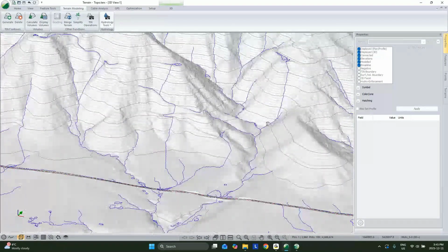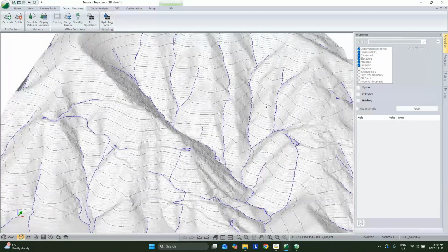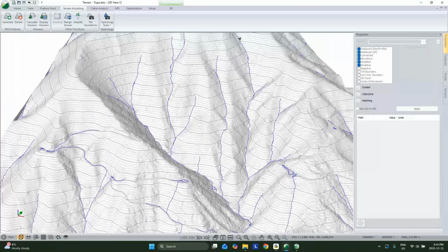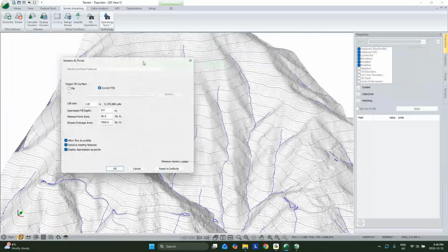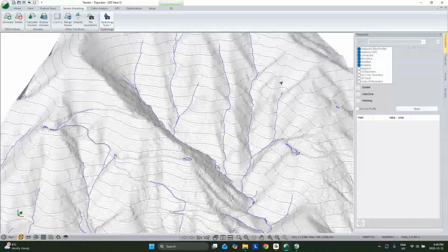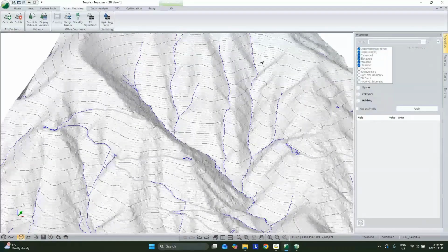And for this tool, it's looking at the minimum area draining to a point. So if we ran that and said, well, in my particular ecoregion, my streams generally start lower in the watershed, we could bump this number up. That's setting the threshold for how large an area it takes to contribute before we see channelization. So I bump that up, we run it, and see the streams go further down. If we decrease that number, the streams would go further up the watershed.